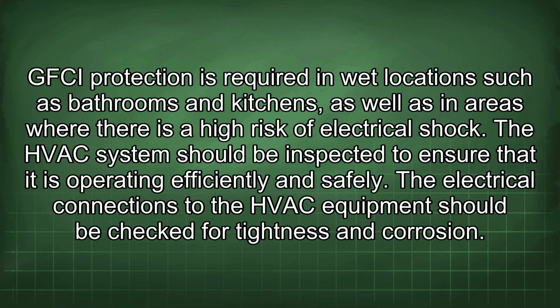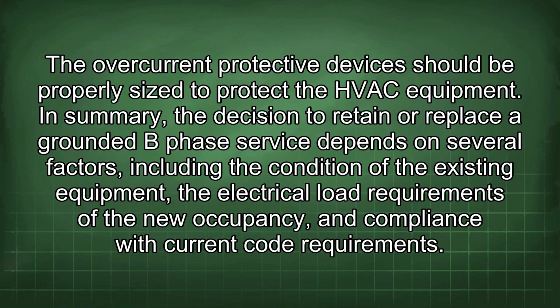The HVAC system should be inspected to ensure that it is operating efficiently and safely. The electrical connections to the HVAC equipment should be checked for tightness and corrosion. The overcurrent protective devices should be properly sized to protect the HVAC equipment.